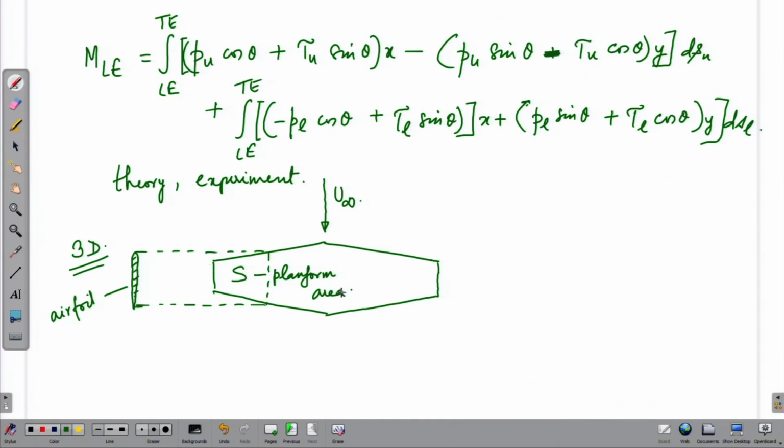Now, if you had a wing where the sectional geometry did not change along the span, then that would be a 2-dimensional wing, so to say, because its section does not change along the third direction. However, here it does, and it also has finite extent, it has tips, it has finite span. These are the two tips, and what you have in between is the span, and it also has a chord which varies along span. So, you can take some kind of an average of the chord as it varies along the span and define something like a mean chord.